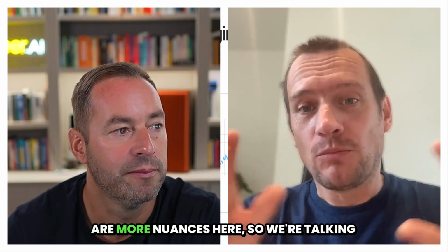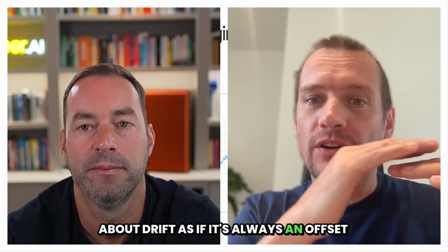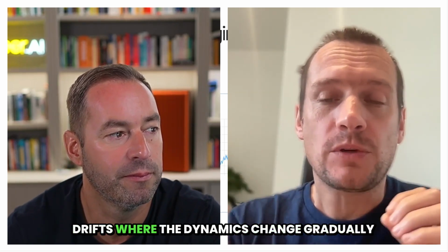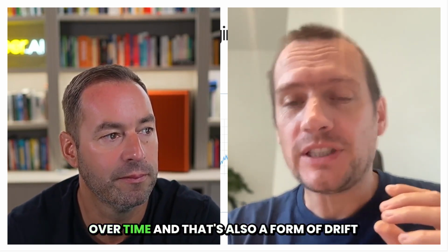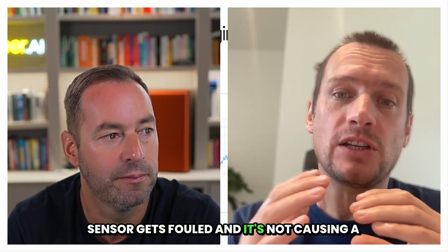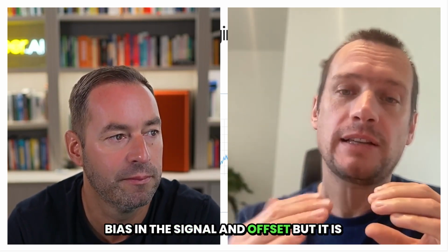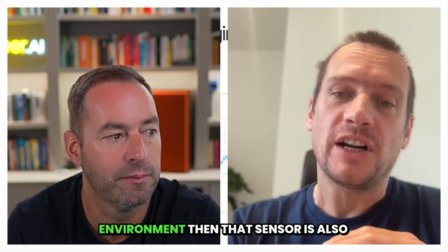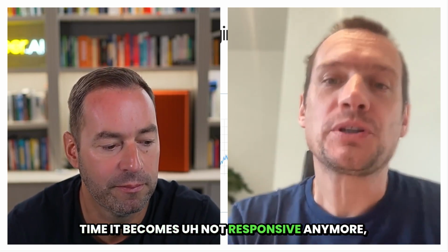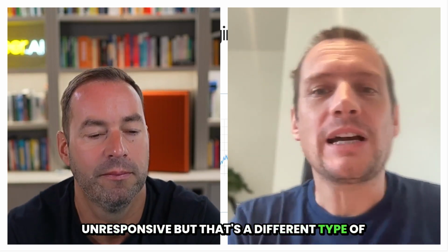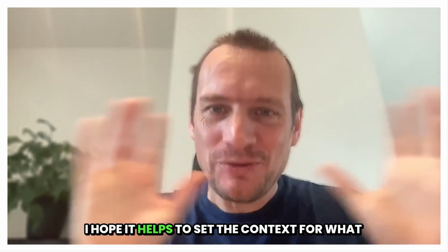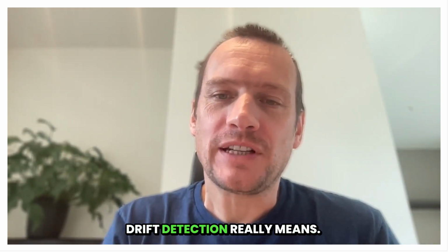There are more nuances here, right? We're talking about drift as if it's always an offset between two signals, but you also have other types of drifts. For instance, you have drifts where the dynamics change gradually over time, and that's also a form of drift that might happen, for instance, when a sensor gets fouled and it's not causing a bias in the signal, an offset, but it is reacting more slowly to changes in the environment. Then that sensor is also starting to misbehave and drifting over time. It becomes unresponsive. But that's a different type of drift also to pick up. So anyway, there were some complications. I hope it helps to set the context for what drift detection really means.